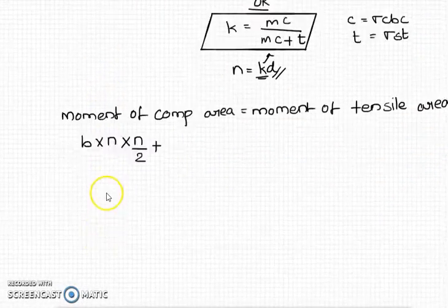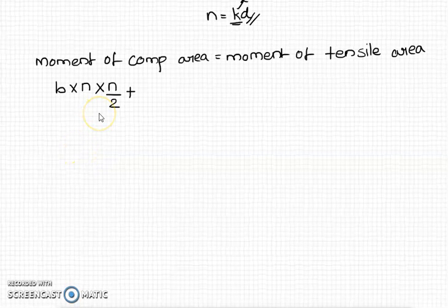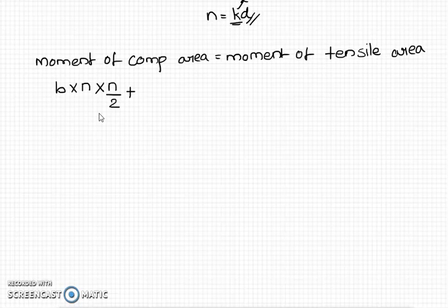Okay, so here this will be equal to, first the total area of the rectangle, then we will add the area of steel. Now when adding the area of steel, we have to consider the modular ratio, that is MC into ASC, as it is the area of steel in compression, and it will act at N minus DC from